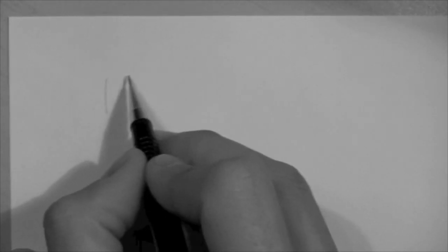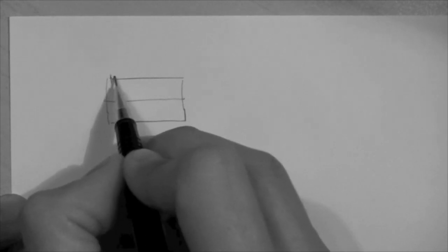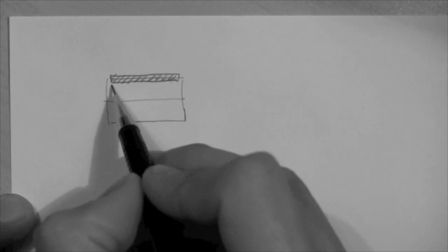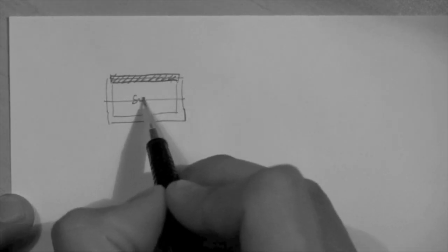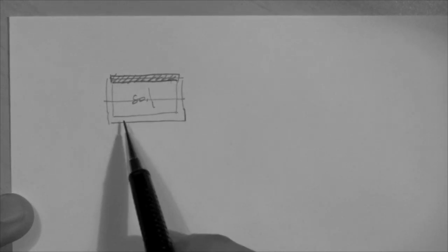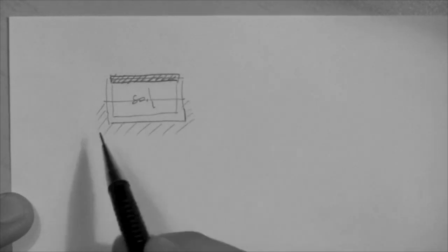Direct shear. So, as you've seen in the video and in the lab, we have a box. The box is split in half such that the top part can move relative to the bottom part. The top part is open, so there's a plate that rests on the soil specimen, which is here. This line here is to show you that the bottom of the box is separate from the top. The bottom is fixed. Sometimes the top is fixed and the bottom moves. Sometimes the bottom is fixed and the top moves. That doesn't really matter.